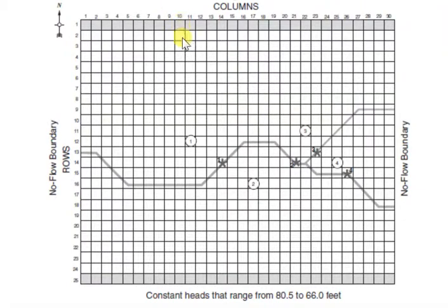This is a valley with a stream running through it, indicated by the gray line. Specified head boundary conditions on top and bottom produce a sloping condition. The MODFLOW simulation of this system includes recharge over the domain, and the stream is modeled using the STR package. The system is modeled as one layer, which has transmissivity independent of head.